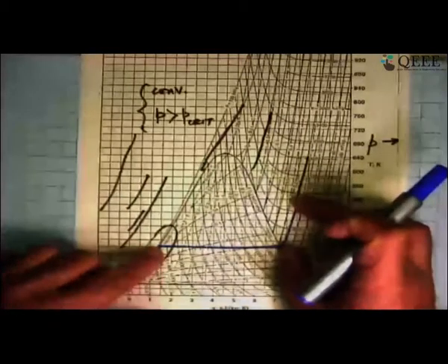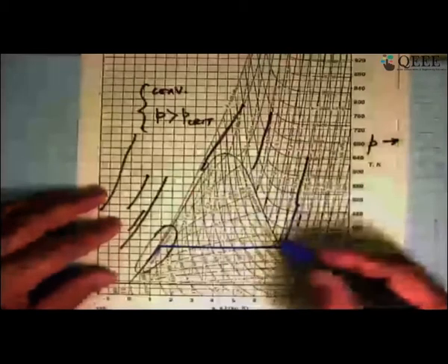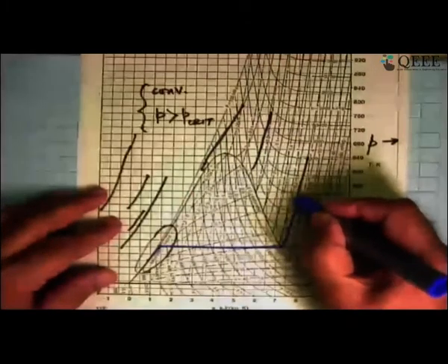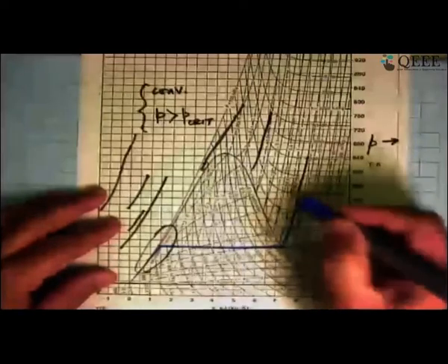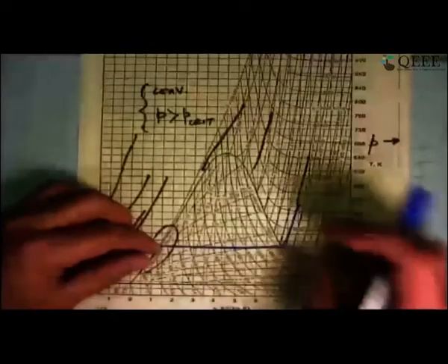And then we design another part of the device which will do the heating of the fluid from saturated vapor state to superheated vapor state. And that's how, whether it's a boiler or whether it's a feed water heater, we end up designing everything as 3 series heat exchangers which do this job. We have learnt about this, we have learnt about this. Now we will look at what happens here.